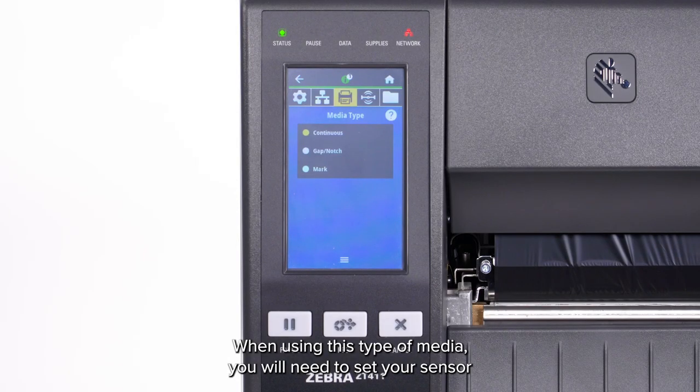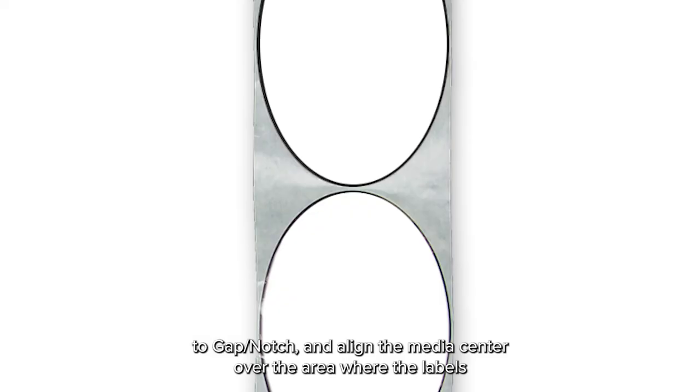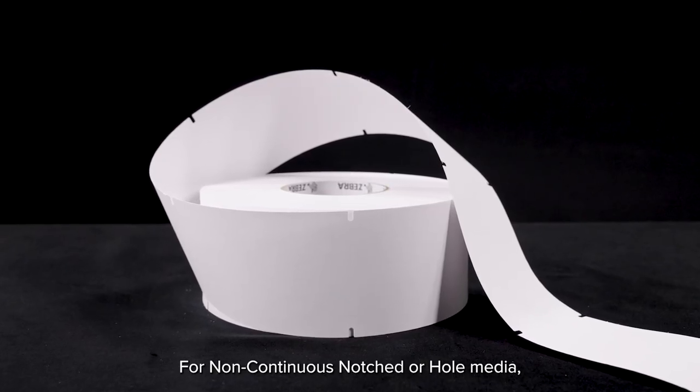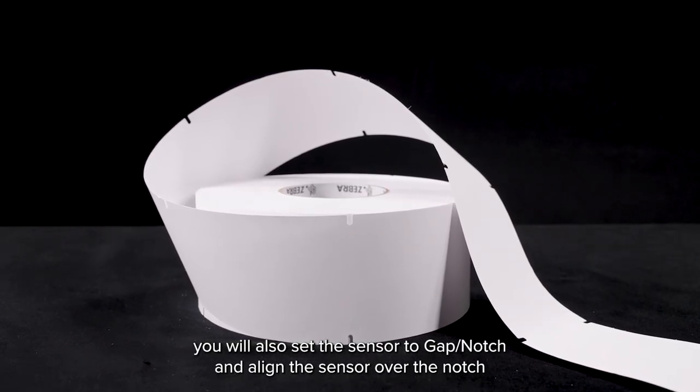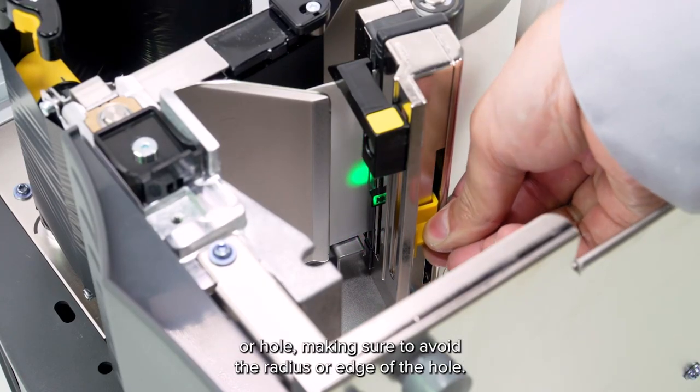When using this type of media, you will need to set your sensor to gap notch and align the media sensor over the area where the labels are closest to each other. For non-continuous notched or hole media, you will also set the sensor to gap notch and align the sensor over the notch or hole, making sure to avoid the radius or edge of the hole.